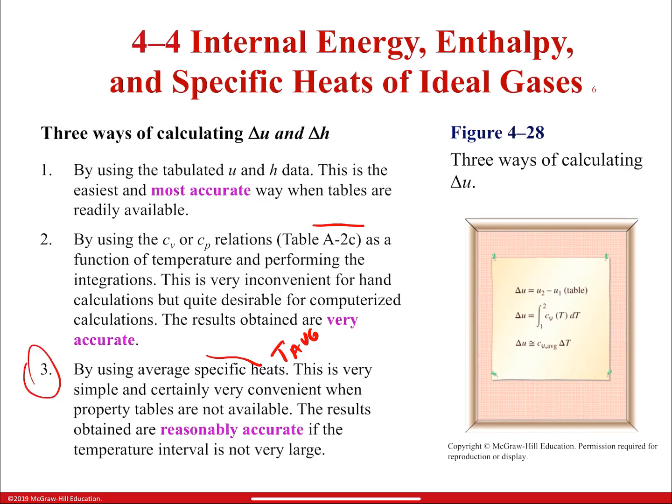So pretty much the first and second are the ones that we use for Thermodynamics 1. You have the tables when they are open, for water or refrigerant 134A. And when they're not available, we use the equations I just gave you. Just remember that, guys, because I've seen people using the equations when the water tables were open, and that's why they don't reach the right results in the exam or the regular exercise. So when working with ideal gases, this is the one that we need. When working with water or refrigerant 134A, that's the one we're going to be looking for.